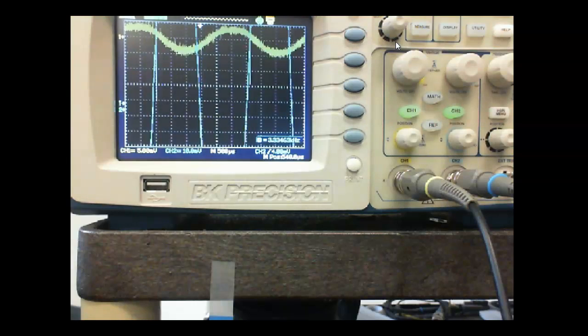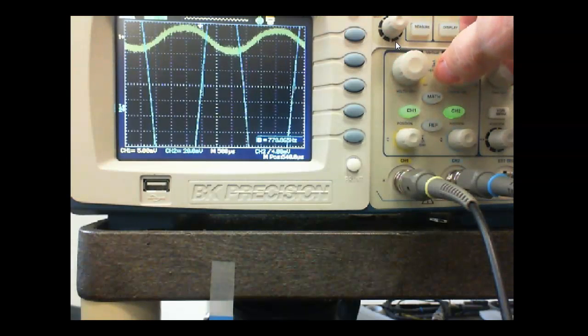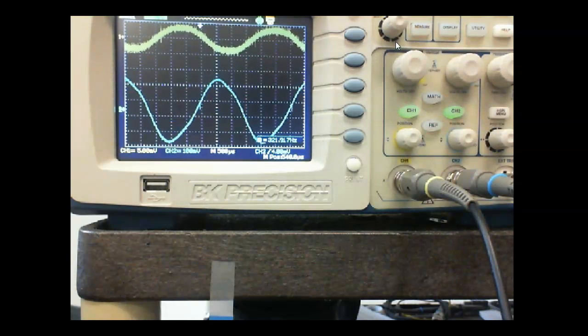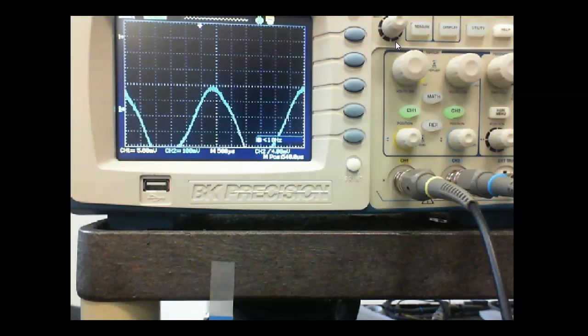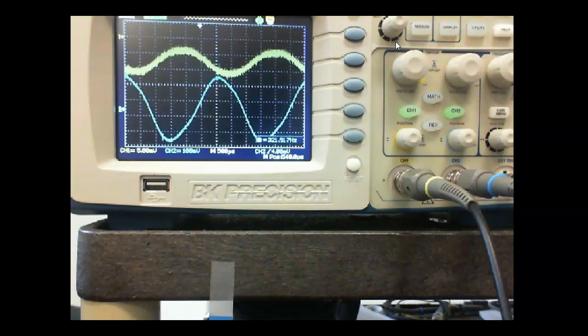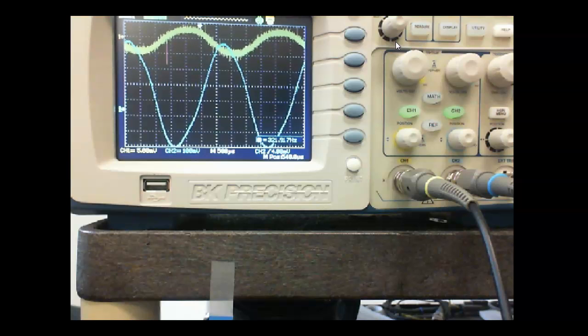Higher. The voltage goes up. And why is that? Yeah, because now it's going to be RC over RE prime, right? A while ago it was RC in parallel with the load. So here comes the load. And the gain went up. That was step 9, right? Yeah, because we removed the load.